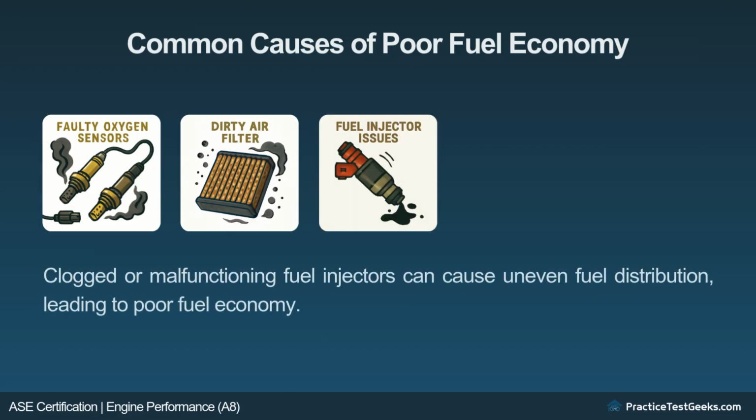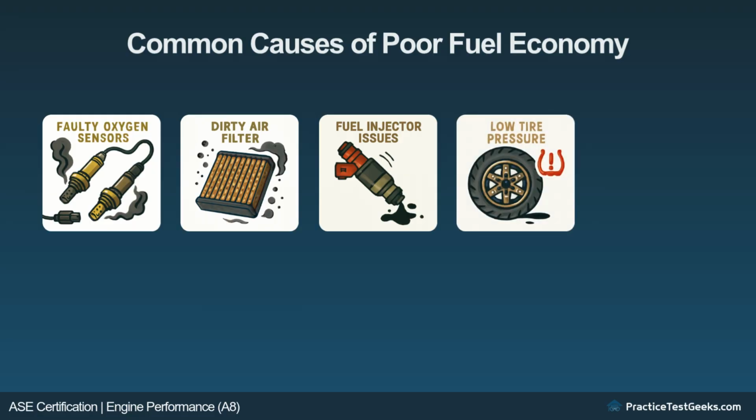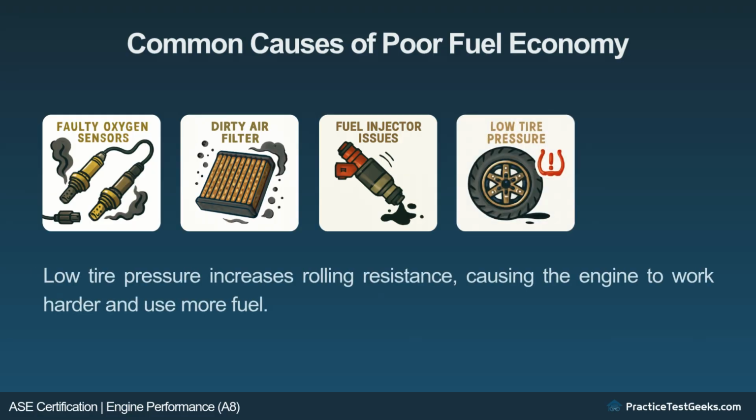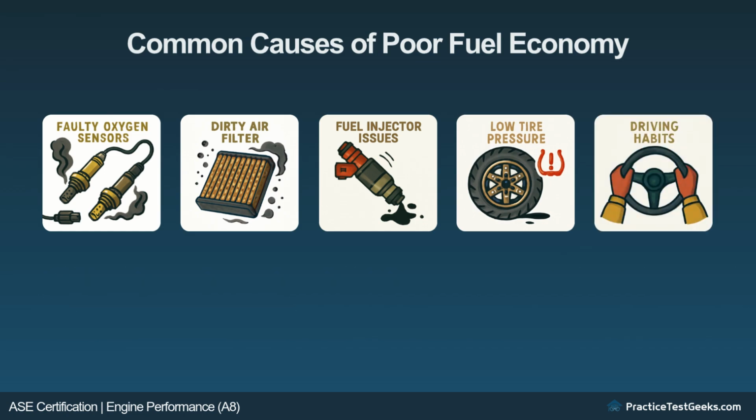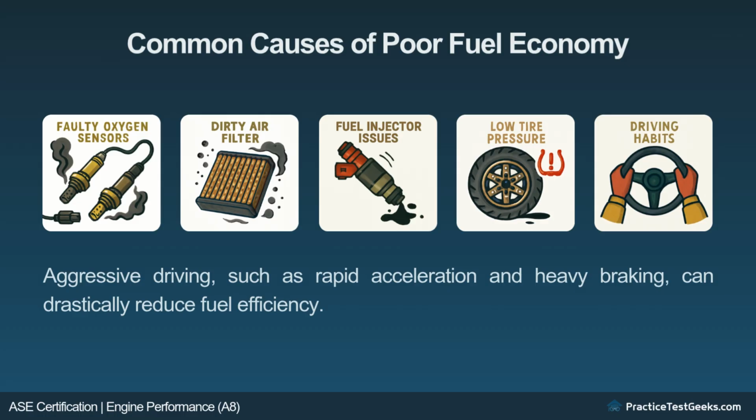Fuel injector issues. Clogged or malfunctioning fuel injectors can cause uneven fuel distribution, leading to poor fuel economy. Low tire pressure. Low tire pressure increases rolling resistance, causing the engine to work harder and use more fuel. Driving habits. Aggressive driving, such as rapid acceleration and heavy braking, can drastically reduce fuel efficiency.